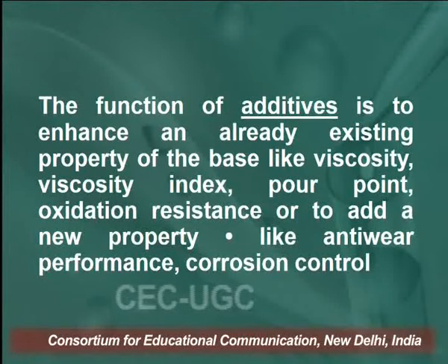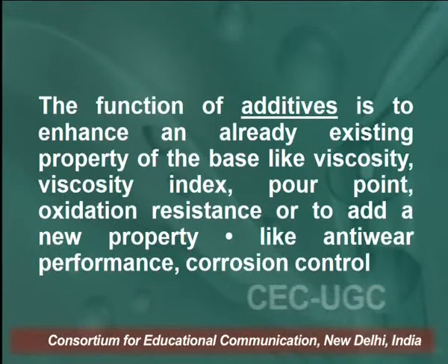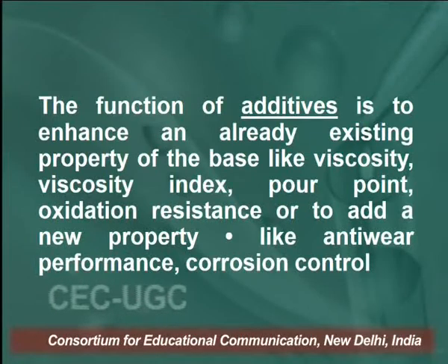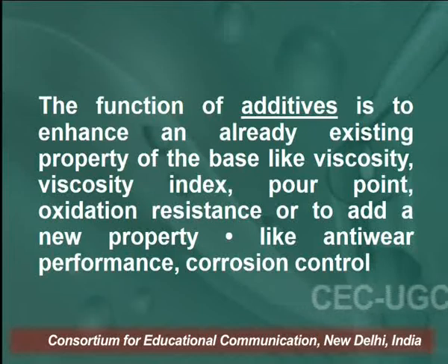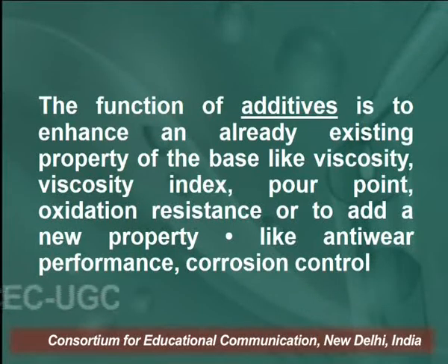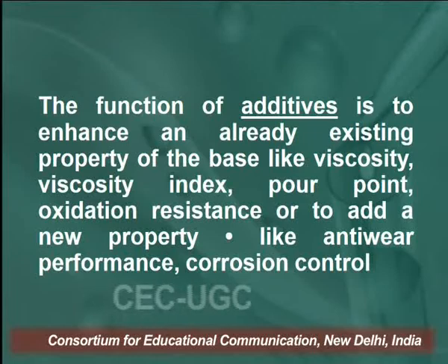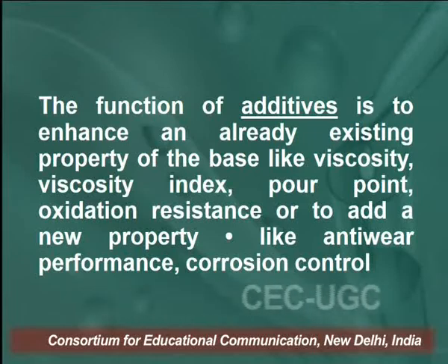The function of additives is to enhance an already existing property of the base oil like viscosity, viscosity index, pour point, oxidation resistance, or to add a new property like anti-wear performance, corrosion control, etc.